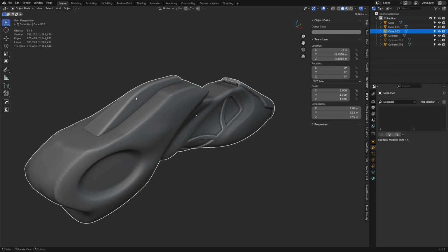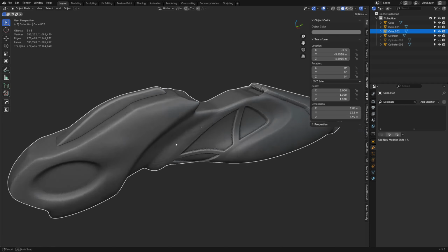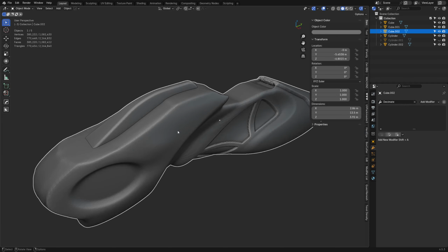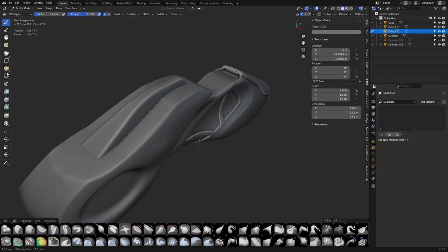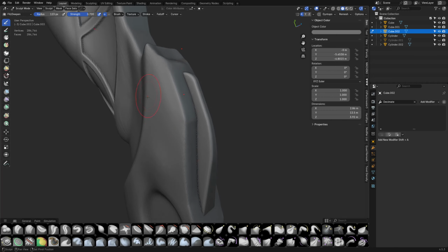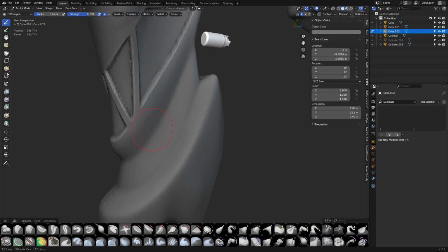You don't necessarily always need to sculpt. This piece down here obviously wanted to be sculpted, but if it's something more like this one, just model it. That's the easier way to go. Just Control R it. I think it's a little high resolution at 300,000, so I'm going to keep that in check by adjusting it to a value I want. Not really a big deal.